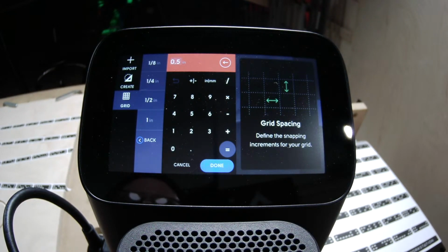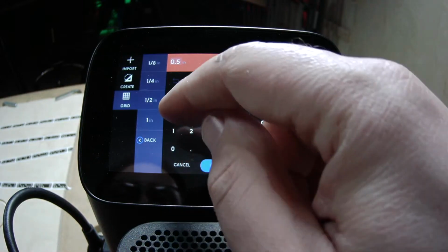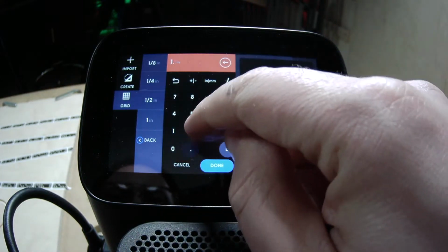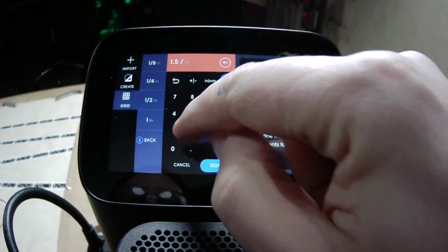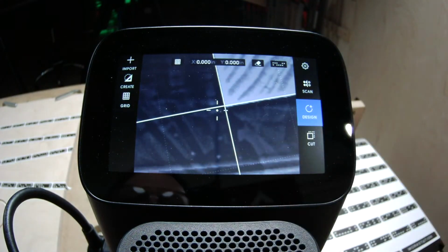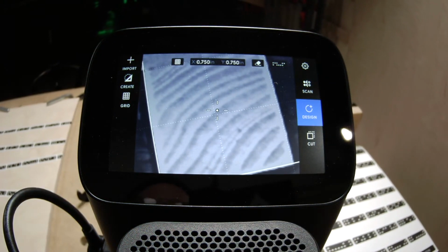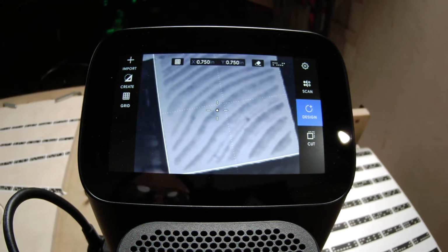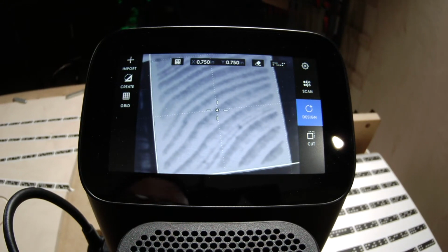So I am going to make a grid that is the size of my tenon divided by 2. So it's 1.5 inches by 1.5 inches. So I'm going to go 1.5 inches. And actually, this is a calculator, so I'm just going to go divided by 2. That's 3/4 of an inch. But in case it was a more complicated bit of math, it's really handy to have the calculator. And now what I've got is a point that's right in the middle of my tenon.